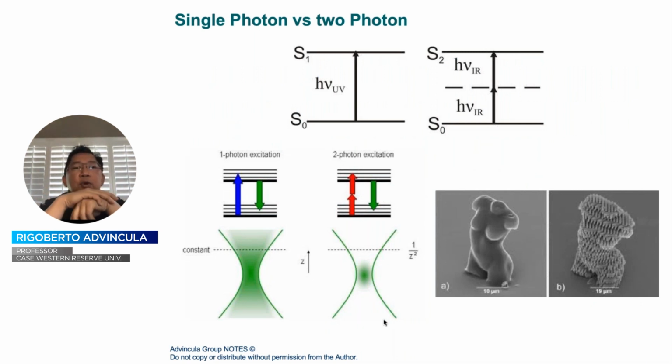Now, I explained earlier that photopolymerization is quite popular. What I mean by this is single photon polymerization. That is, excitation for one photon release is equivalent to one initiation process or generation of one radical. Now, we have another type of photopolymerization which is based on two photon. This has to do with regulation and excitation of light, in which two photons will result in one excitation. And what this means is that one is able to control basically the focal point very precisely, even using confocal type of microscopy methods to regulate the generation of the radical species in a very confined space or time.